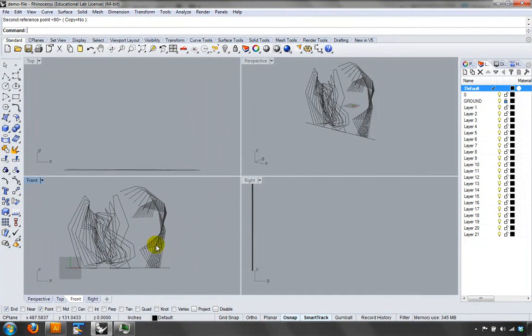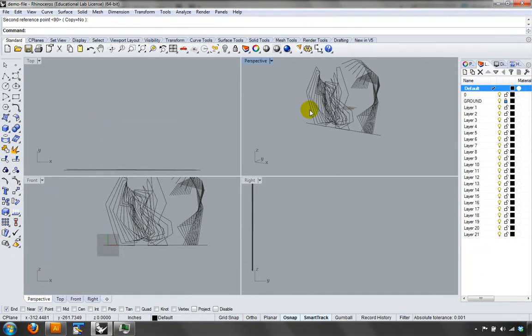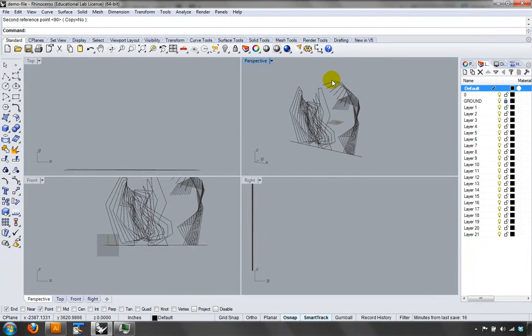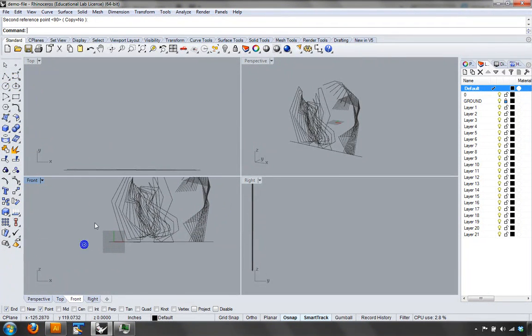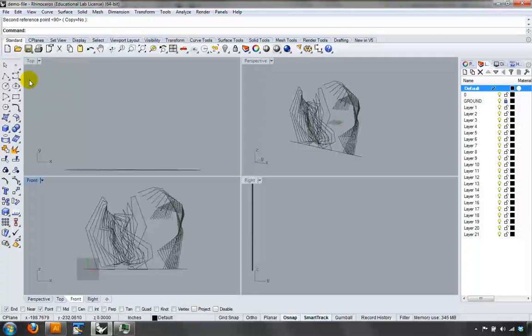The next thing we're going to do is scale these to proper dimension, and to do that I need something so that I understand how tall they need to be. I could use some math to figure out the difference between this height and, let's say, 6 foot, and then calculate the scale and type it in as a decimal using the scale command. But that's pretty hard. What I'm going to do instead is draw a 6 foot tall line, and I'm counting this as 6 foot. Yours might be a little bit different if you have people that are jumping. Find a reference, you might even say that's like 8 foot 6 inches, find some number that you can scale to and draw a vertical line for that.